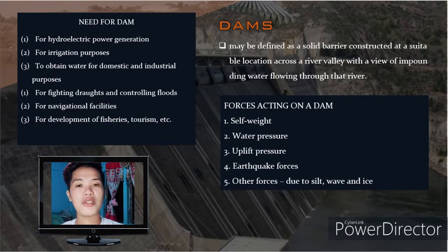The various forces acting on a dam involve its self-weight, water pressure, uplift pressure, earthquake forces, and other forces due to silt, wave, and ice.